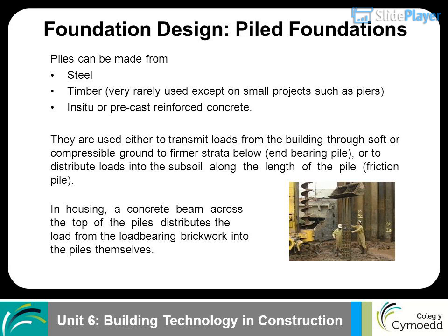Piles can be made from steel, timber, very rarely used except on small projects such as piers, in situ or precast reinforced concrete. They are used either to transmit loads from the building through soft or compressible ground to firmer strata below, end-bearing pile, or to distribute loads into the subsoil along the length of the pile, friction pile.